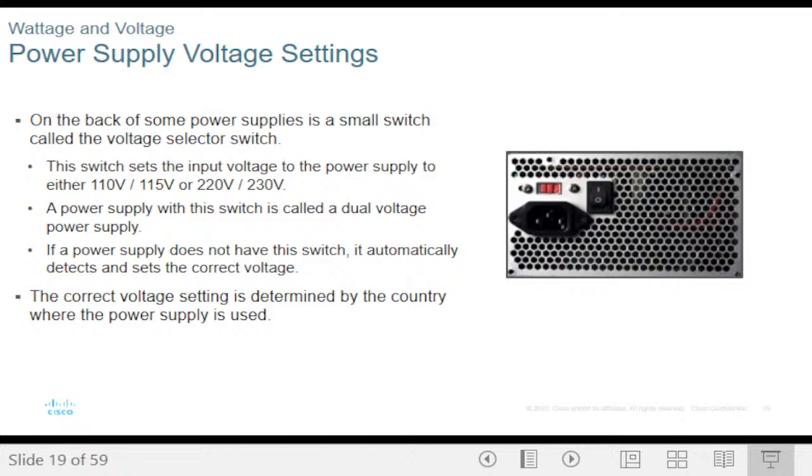So I've had experiences when I was just starting to work with these things, where when it was shipped from, for example, the US, it was rated at 110, and then you didn't pay particular attention, just to realize that you are plugging in 110 to a 240, and so it will just blow up from the word go.